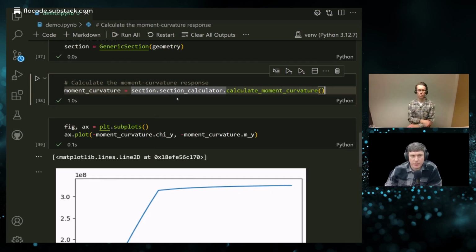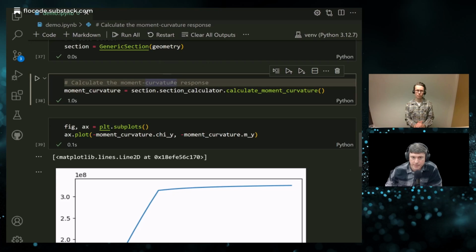So there's a lot of really useful methods in here that can take your output, whatever structural analysis tool that you're using, whether it's simplified hand calculations or advanced finite element models, you can take those outputs and then use the methods in here to either double check your results or to ensure compliance with whatever design code you're using. And in your case, it's Eurocode 2. Yeah, I think that's a typical workflow that you described there. So one workflow could perhaps be that you're actually using this as a post-processing tool.